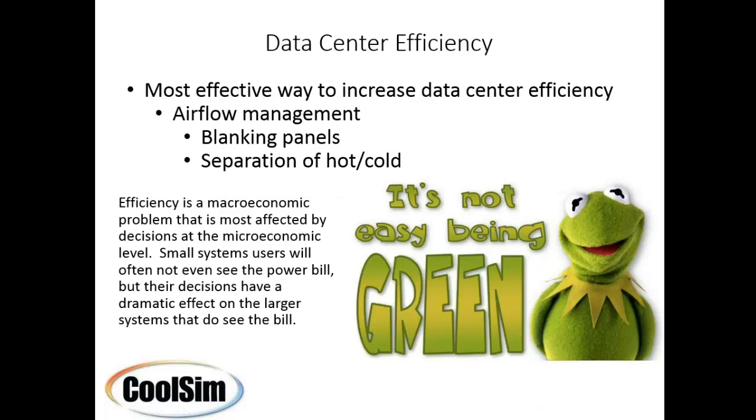Okay. So as I was saying with the whole funding model, data center efficiency, it's not easy being green, and as many of us know, if you ask a data center manager what's green about a data center, the answer they would immediately give you would be nothing, nothing at all. But there are things that we can do to try to make things a little bit more efficient, or in some cases a lot more efficient. But typically your low-hanging fruit on that is your airflow management, blanking panels, your separation of hot and cold. So trying to figure out the most effective way to do that, it's kind of the puzzle that a lot of us are trying to solve here.